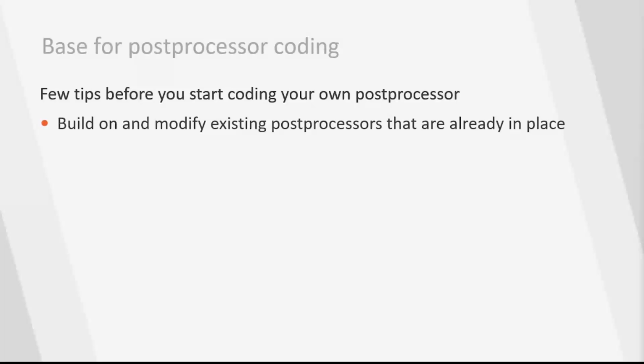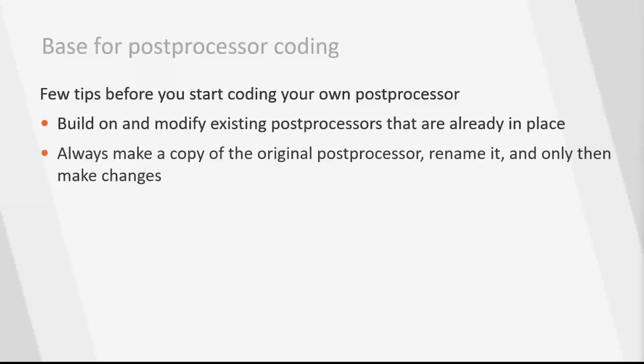Always make a copy of original postprocessor. Rename it and only then make changes. Because if you write code directly on the primary postprocessor code, a new installation or upgrade might rewrite it, and you will lose your work. So never code on the original postprocessor file.